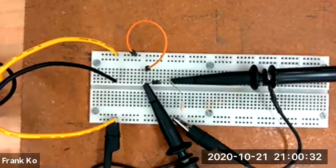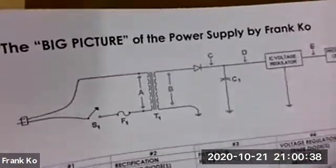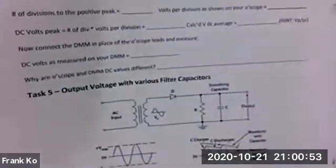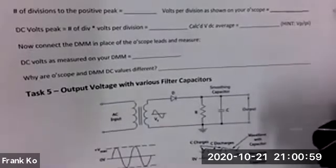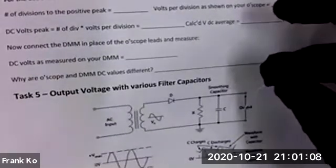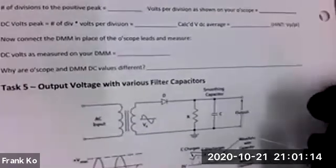And if we look at our drawing of the big picture of the power supply, we should be able to see that the capacitor comes after the diode and is going to be in parallel with whatever source resistor we hook it up to. So let's go ahead and look at our lab sheet. Our lab sheet shows us exactly the same. Our capacitor will be connected across in parallel with the load resistor. And you want to do this. You want to make sure that the long lead is attached to the top of our circuit, the more positive side, if you will, and the black lead is on the negative side, marked as ground on the schematic.